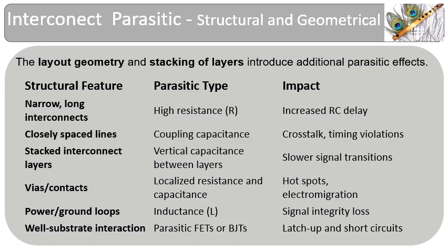Well substrate interference: as analog and digital circuits are mounted on a common substrate, the switching current IR drop and the substrate resistance create interference. The noise thus created is coupled to the sensitive analog circuits, which will experience performance degradation.